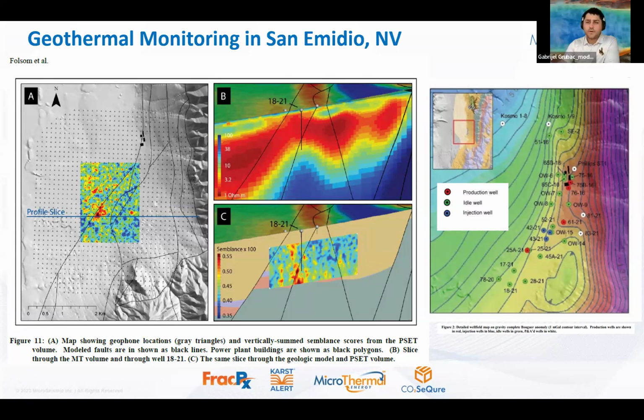All right, thank you. We got a question that came in from Nestor Ruiz. It's a great presentation, Jonathan. One question about the tortuosity around the pipe or the hole: if you do a gun orientation in the direction of the fracture, and then do the fracturing, in your experience, will that improve the fracturing distance, decreasing the tortuosity around the perforations?